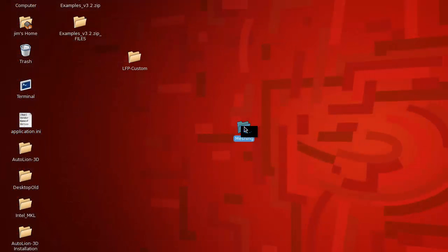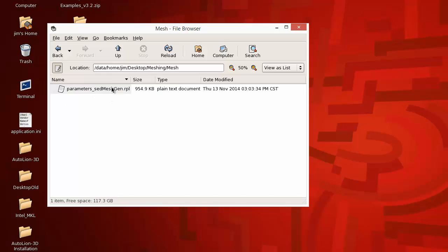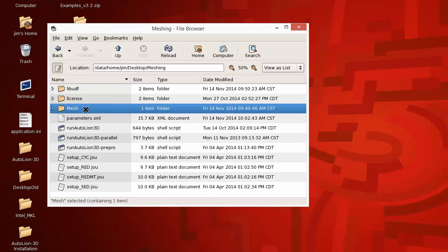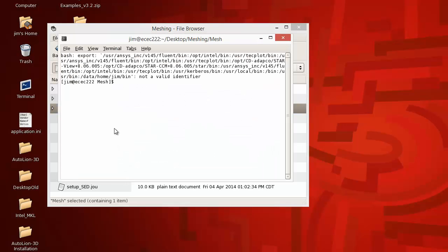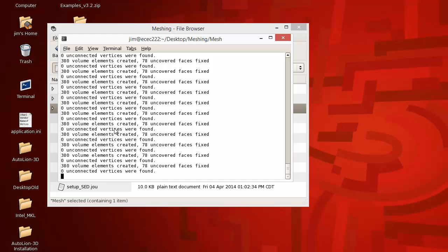Start the mesh generation process by opening a terminal window in the location of the script file and run the following batch command in ICEM. In this case, I'll use the name of the script file we saved here. This process will automatically generate the preliminary attribute and geometry files for the mesh creation process.